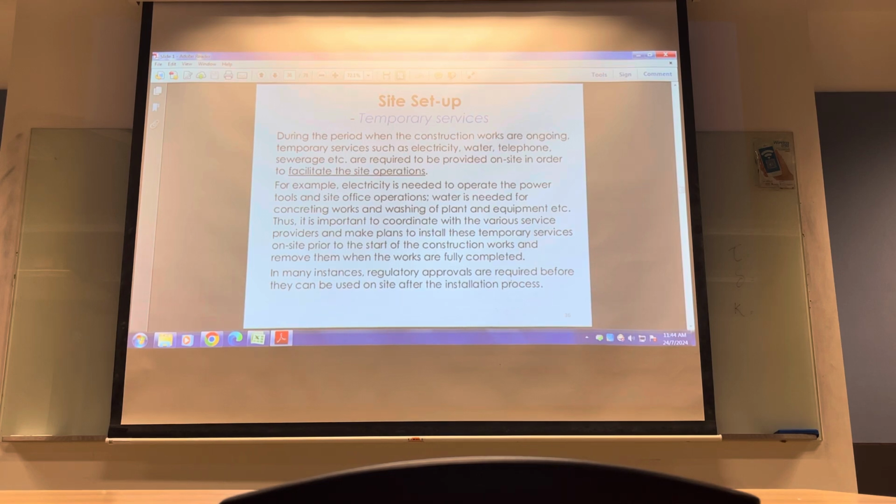The crane access. You may have heard about accident of crane due to improper access. The access of the road that cannot sustain the load, causing the crane to topple. Once crane topple, it can create a lot of damages to the building, to the facility, to human lives.